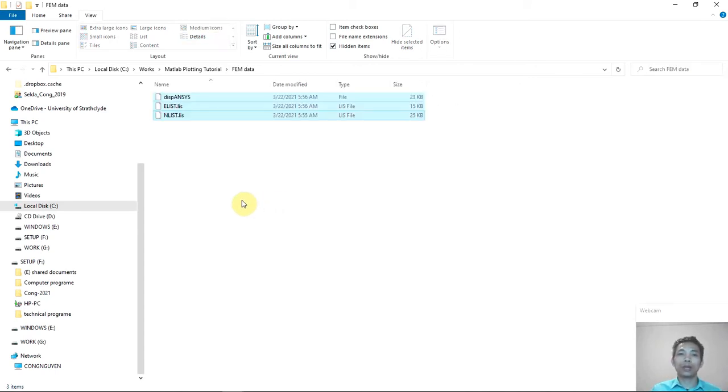If you use Abaqus or whatever programs, please try to learn how to extract nodal connectivity and nodal coordinates, and also other information like displacement, rotation, or velocity field. For example, ANSYS Fluent can also allow us to do that.